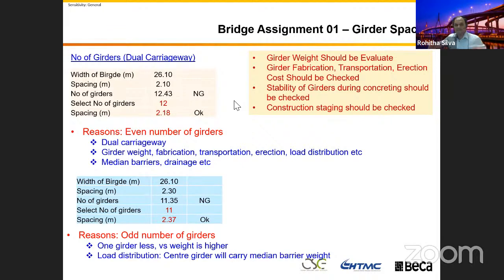Because we calculate the bridge width, we select, we're going to discuss as the first option, the beam slab type bridge. Then we're going to look at 1.8 and 1.5 meter girders. That is quite common in the industry. We want to look at these two options. Then we need to calculate the number of girders. Now we already did, right?